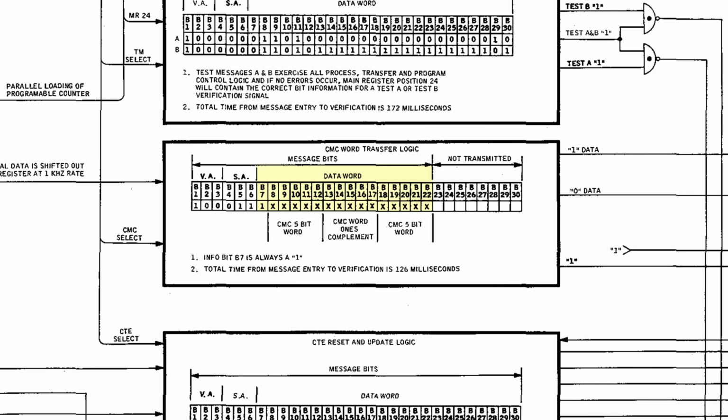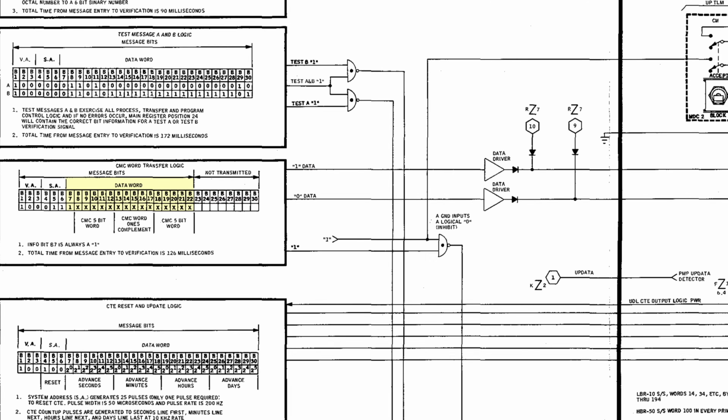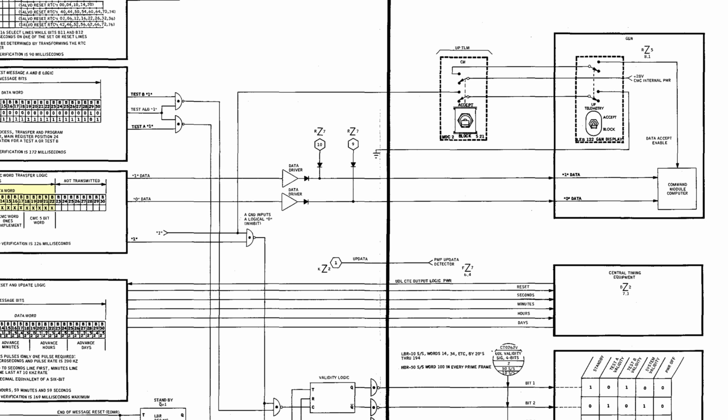The resulting 16-bit data word was transmitted serially to the AGC by pulses over 2 wires, one to input a 0 and another one to input a 1. The AGC was then responsible to check for validity. Note that 2 switches, one on the command panel and one in the lower bay, had to be set both to the accept position in order to grant remote access to the AGC. Generally, that was not the case, and the ground had to specifically request computer access before they uploaded anything, and access was turned off right afterwards.